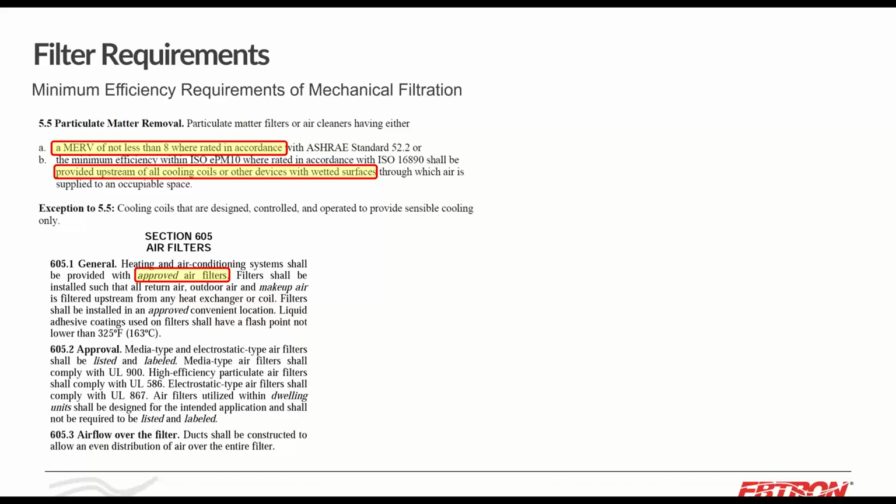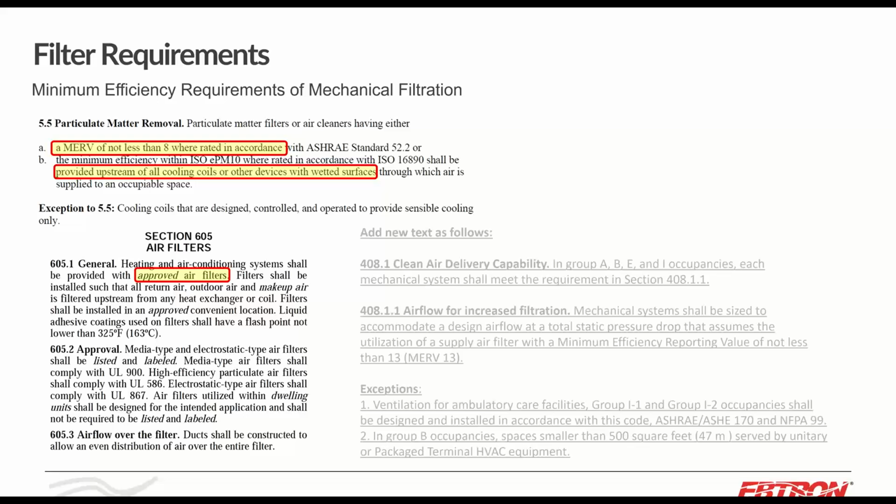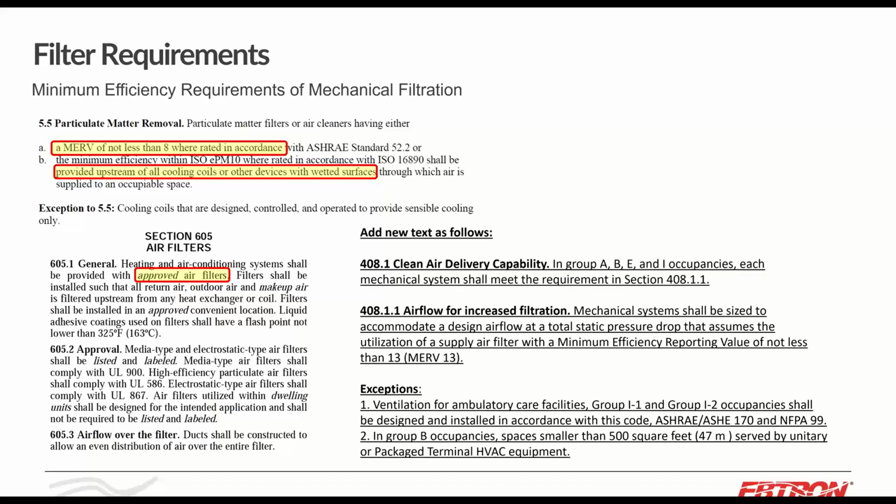In the IMC, it only says approved filters. There is no requirement for a minimum. There was a requirement that was put forth for the next version of the IMC for a MERV 13 filter. Unfortunately, the ICC had voted this down. They got some suggestions from concerned people that MERV 13 was a little too high, so we're back to not